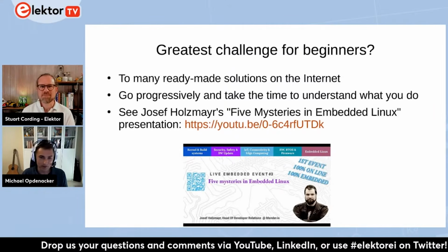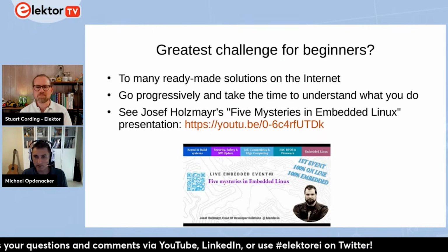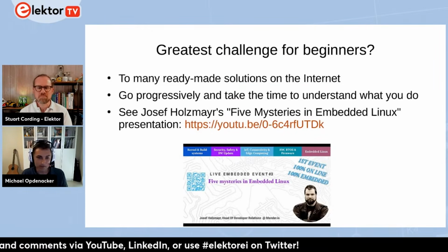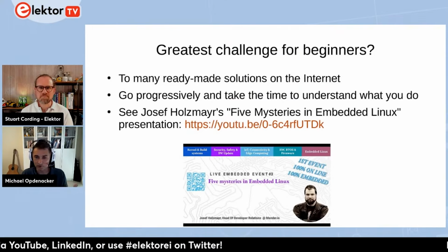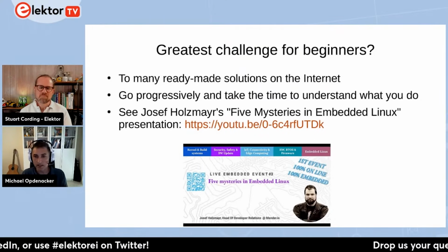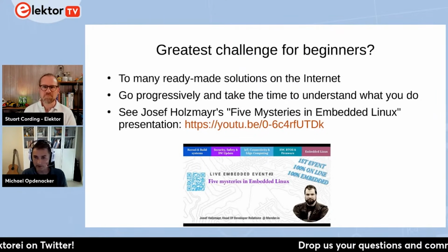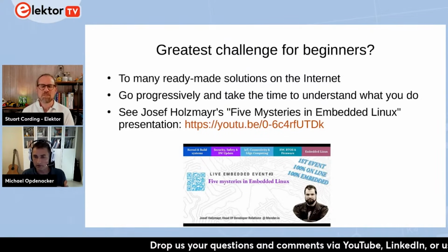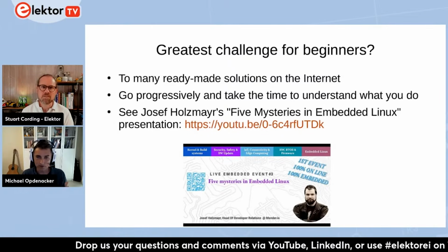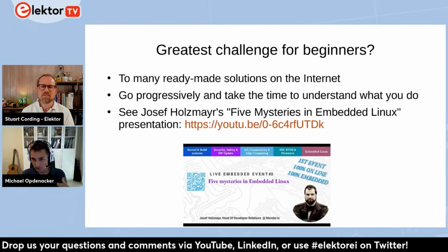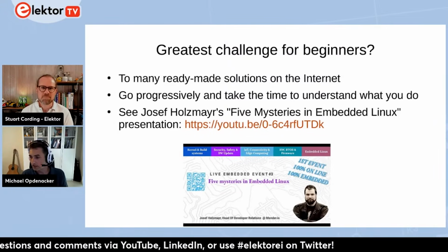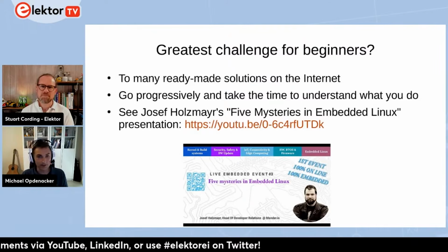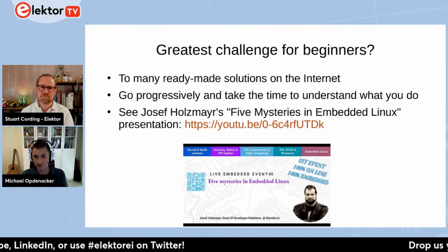You can start by studying existing code, with a simple I2C device, for example. That's a good way to start. You see how this all fits together, how the kernel recognizes the device, and how you can support multiple devices within one driver.